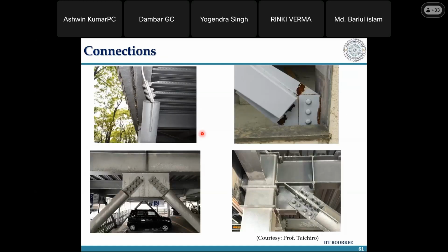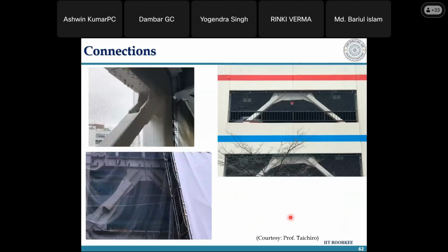These are some connections, with respect to the Christchurch earthquake that we have had. Again, the brace has different types of connections. This is wrong. As I said, the gusset plate should be allowed to bend out of plane or in plane, with a knife plate or things like that. Any stiffener, in newer designs you won't be finding such an approach.